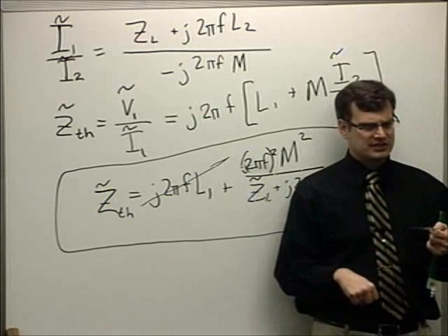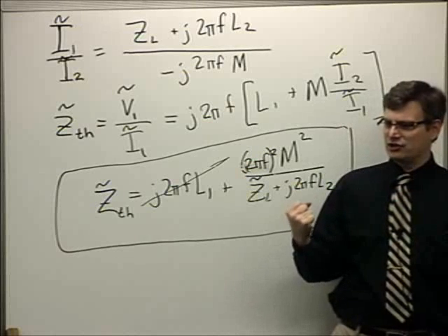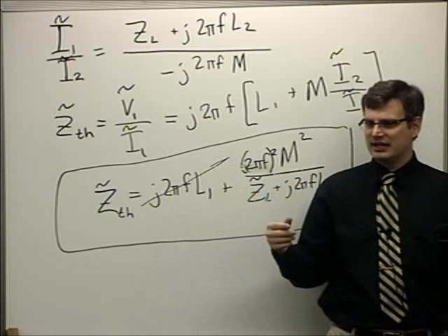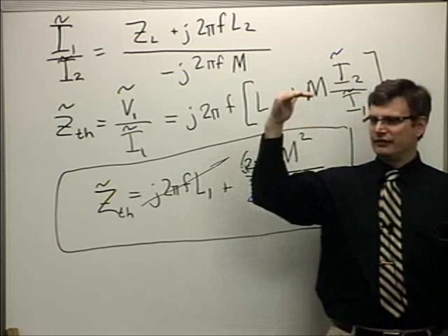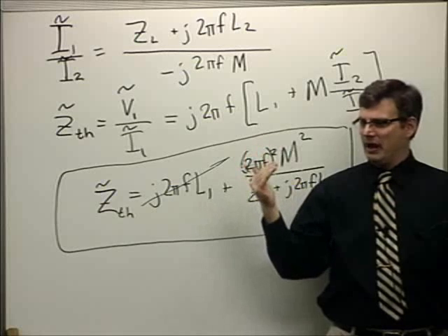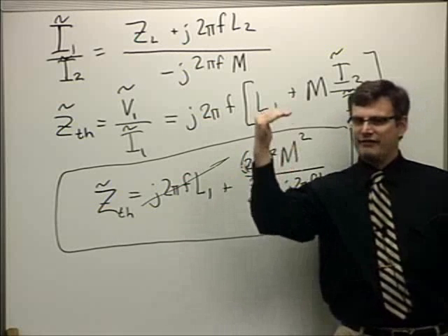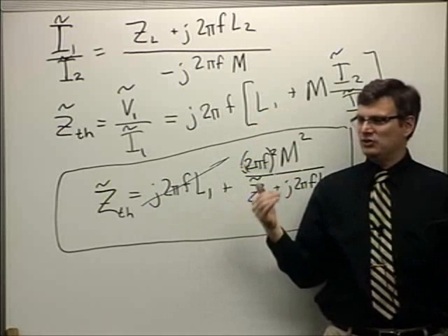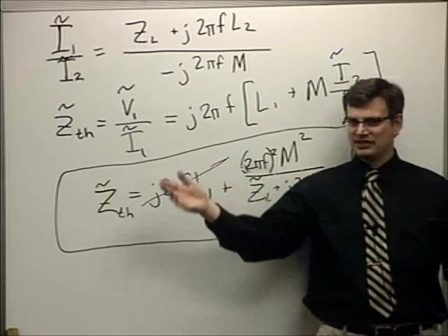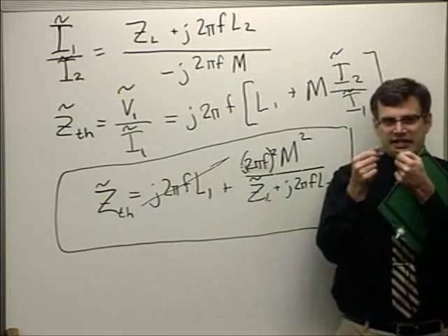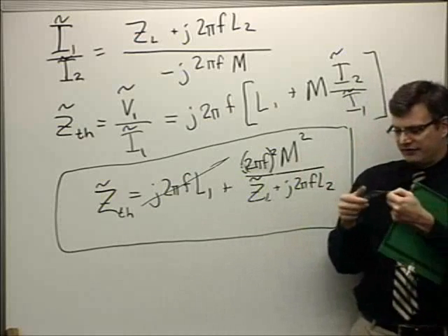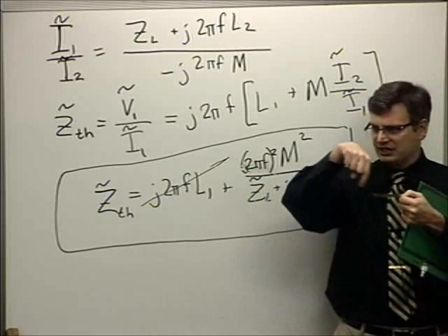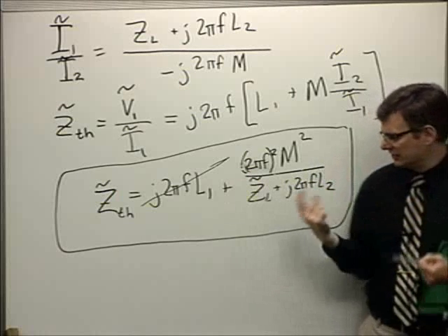Why do you want to loop around 6 times? Well, remember, you've got to turn on diodes for that charge pump, so you want a high voltage. You care a little less about the current because as you increase the voltage, you decrease the current, in conservation of power, right? So you would rather have high voltage than high current. The CMOS devices don't take that much power, but they do take voltage to turn on, as well as the rectifying circuitry. So this thing here energizes itself, and it sees a lot of self-inductance because there are 6 windings here. It's a lot of mutual inductance. So this term is significant.